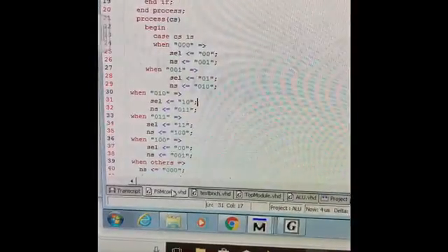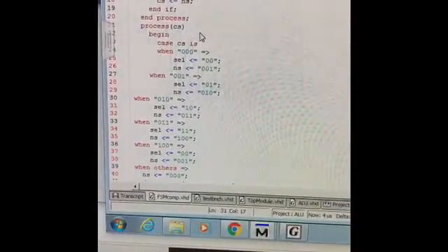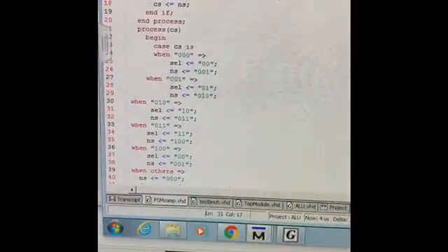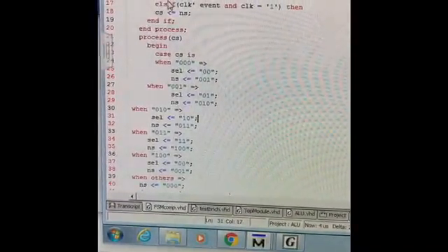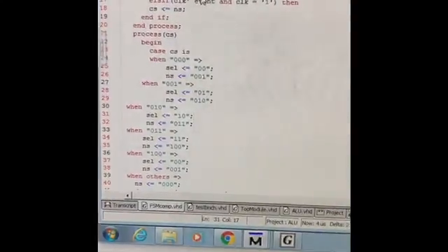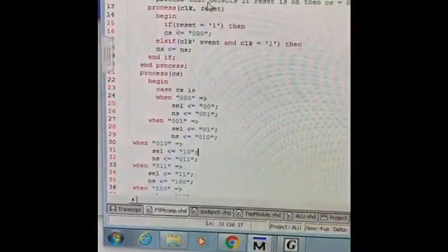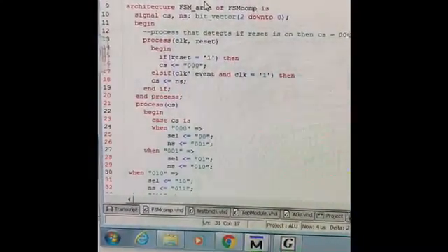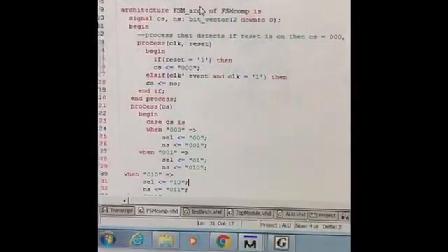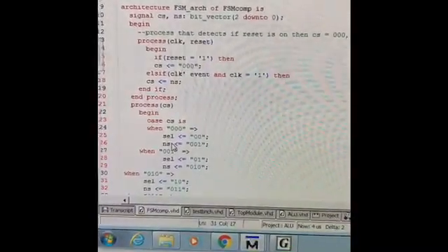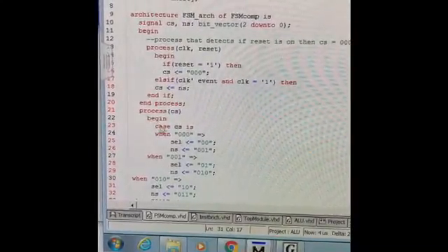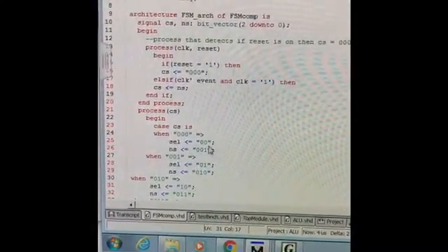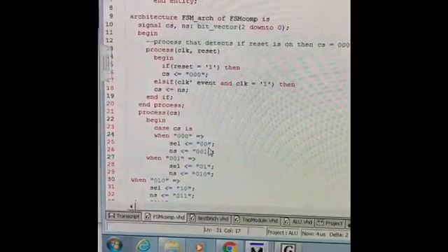So here's our finite state machine. Something that we need to take note of is when the reset is on, then we will be sent to state 0. And because we don't have any inputs, it will go into each state in our test bench. So we should expect when our reset is on, and if it goes to state 0, 0, that the select value will be 0, 0, and an AND function will be performed.